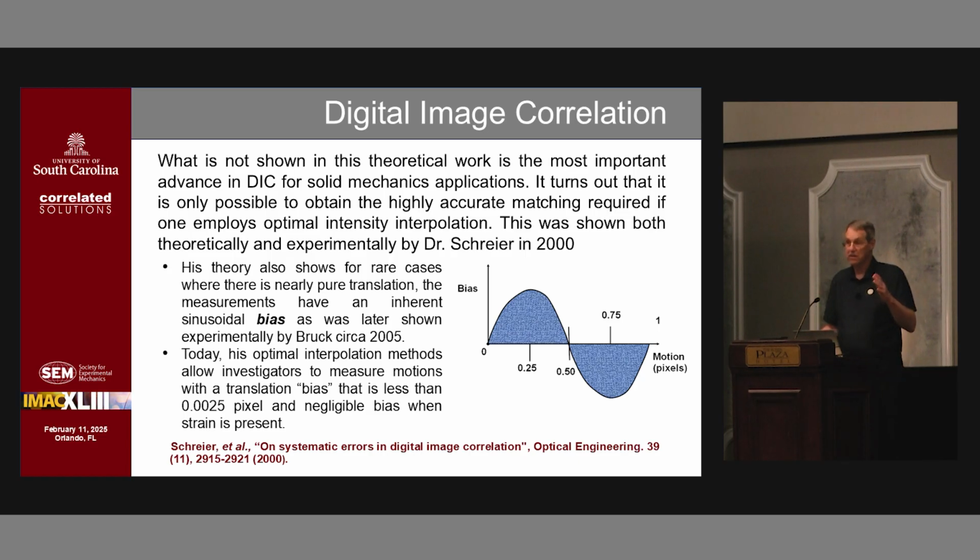So I can tell you that as far as I'm concerned, it is the most important extension or development in image correlation. He proved that an optimal interpolation function selection is critical. If you pick an optimal interpolation function, it will dampen out noise and increase the accuracy of those gradients that you have in your pattern. As a result, by using optimal interpolation functions, the error is no longer 0.01. You can see here, it is down to 0.0025 pixels. It is 50 times smaller. It was a shock.